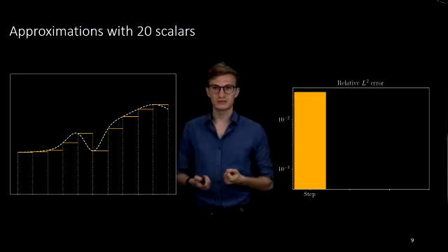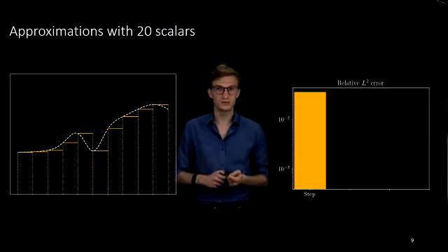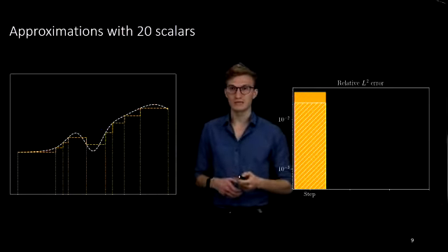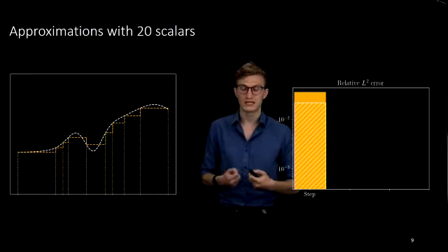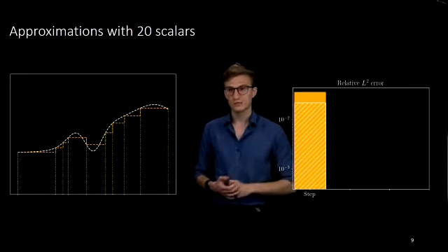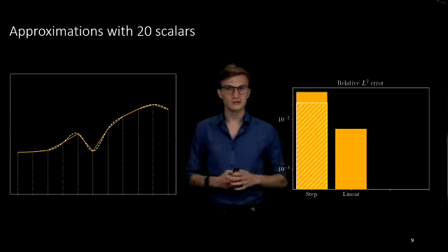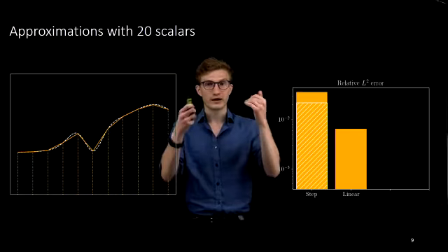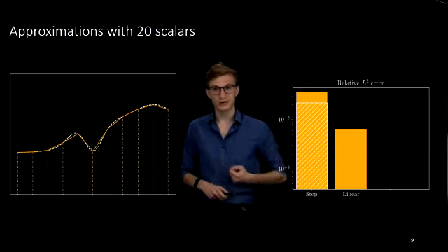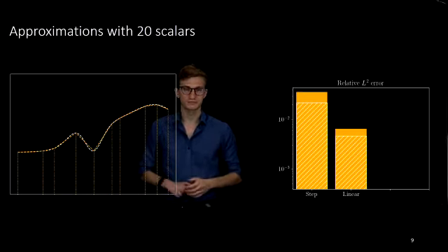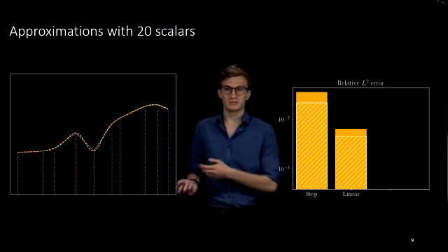If you want to increase the precision of that approximation, we can tune the position of our grid. That's what we do when we are doing adaptive meshing. But still, we get large errors, especially in this area. Another method is to use functions that are one order higher, for instance linear by parts, and then the precision increases, and we can also adapt the mesh. But we still rely on grids.